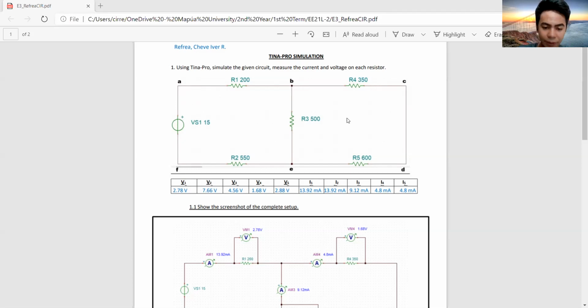In other words, the algebraic sum of all the currents entering and leaving a junction must be equal to zero, as the summation of in equals the summation of out. This idea by Kirchhoff is commonly known as the conservation of charge, as the current is conserved around the junction with no loss of current. So that is Kirchhoff's current law.